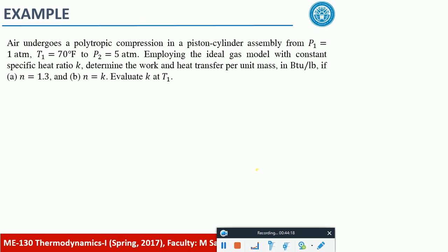Now if you have P and if you have T, would you be able to find out anything about U? How can you find out U, by the way? Yeah, that is CV into delta T. And you can find that constant specific heat, specific heat at constant volume, which was used for delta U. You can have that value from the table, which was I think A-1. That CV is also given there.